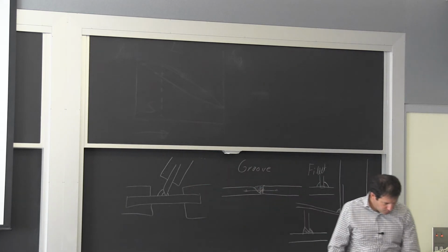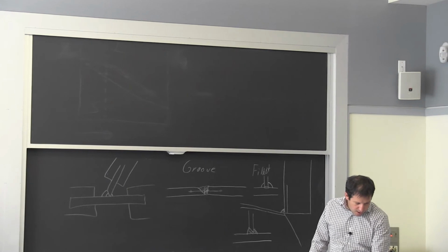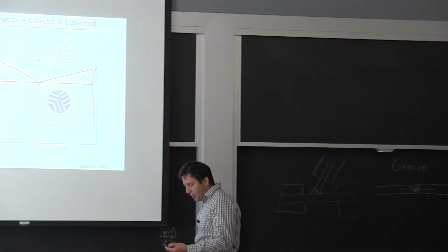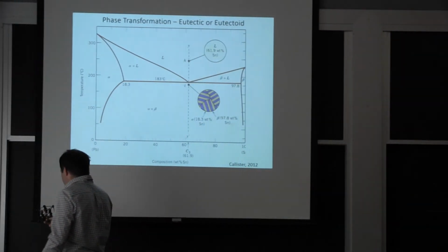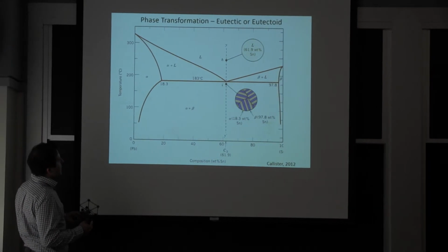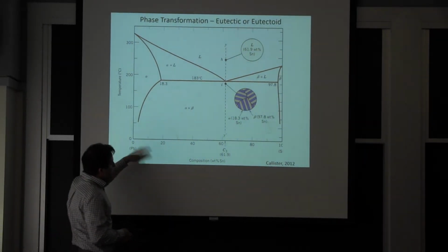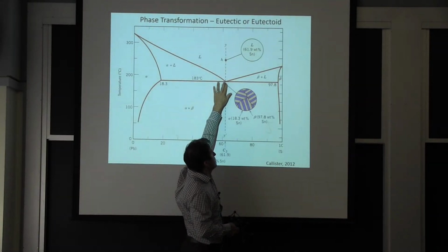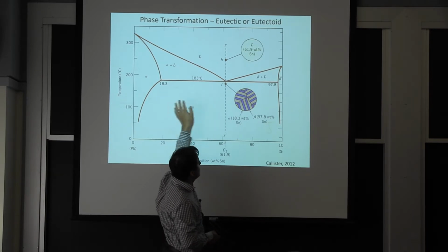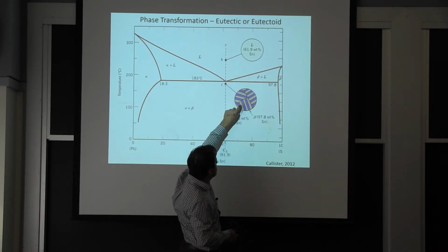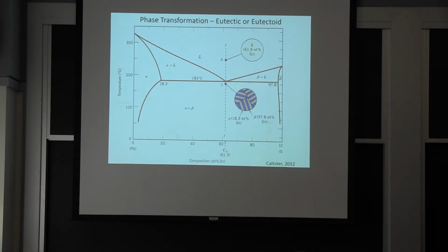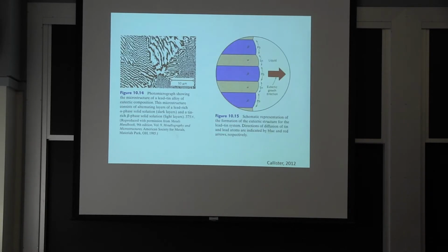All right. So, knowing all of this, you can hopefully understand better if we're forming pearlite. So again, we're going from this to the ferrite, and we have the cementite. This is ideal. This is not the exact composition, but assume for now that you go through the eutectoid. So it's the austenite on top transforming into two zones. We're going to have the iron, and we're going to have the cementite. So it happens simultaneously, and that's why you get that laminar structure. And we have some more laminar structure everywhere here.